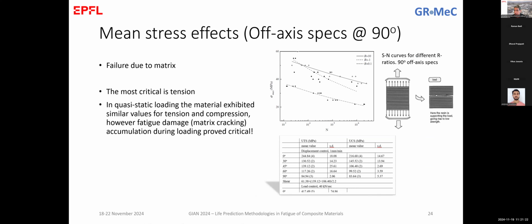One question related to the geometry, what you just mentioned. As per ASTM static testing, there are some dimensions specified for the static testing. So for R equal to 0.1, or tensile kind of testing, we can use D3039, but especially for compression and reverse loading, we should use something similar to D3410 kind of specimen, like a short specimen.